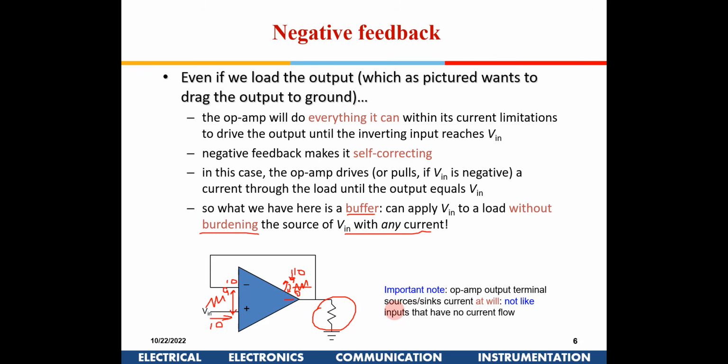Practically speaking, if this is 10 millivolt, it will be 10 divided by 22 lakhs, something like that. That is a very, very small voltage, or you can assume that both are following each other. If you assume this gain to be infinite, then you can assume these two input voltages are following each other.